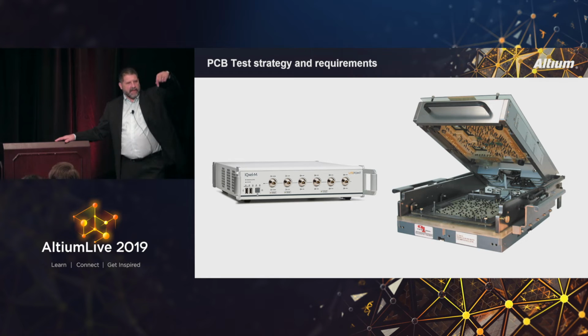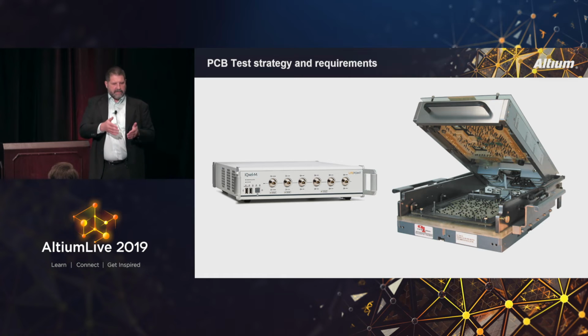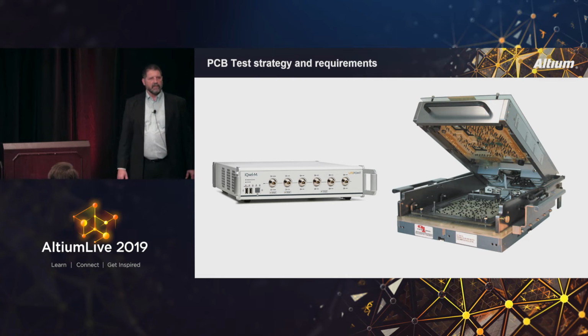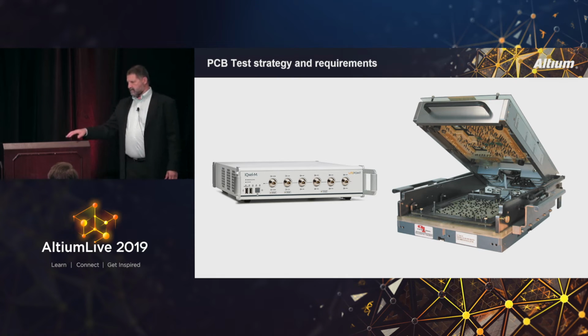No, they have like a diamond shape that comes down and probes, and if it's a little bit off, it's still going to contact that. It doesn't damage the via. It's going to have like 4 sides to it, so it's only minimally touching that via. It's going to touch different quadrants of it, and they control the force that's on that as well, so that it doesn't cause any failures like that. It's not crushing the board. It's not deforming it.